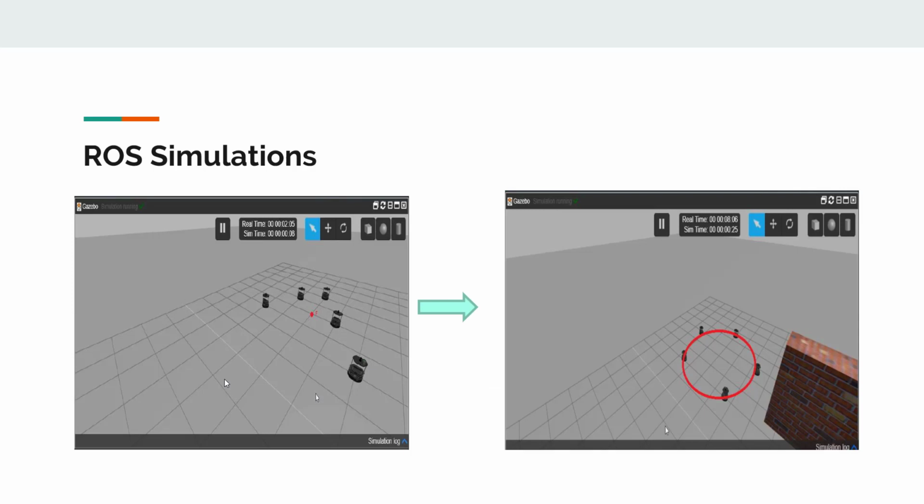So as you can see, this is a snippet of our results from the raw simulation. The robots are randomly distributed. When these robots go through the consensus equations that we have derived, they calculate the consensus point F, and based on the consensus point F and the defined radius, they agree on forming the circle. This is the final result of the formed circle.